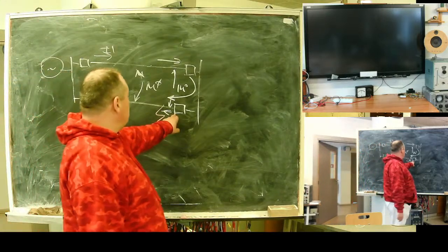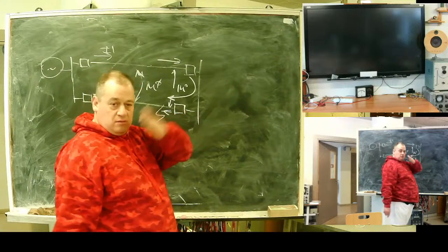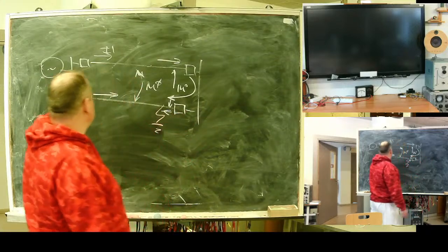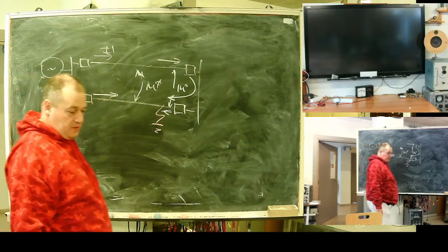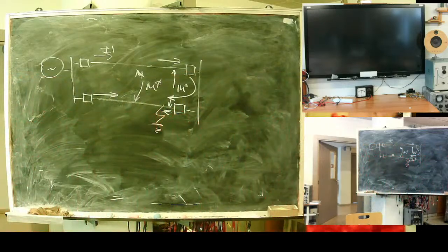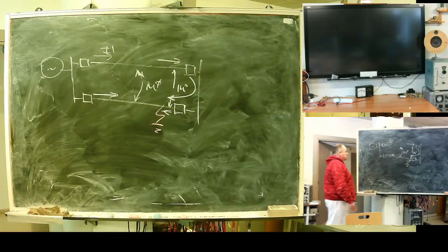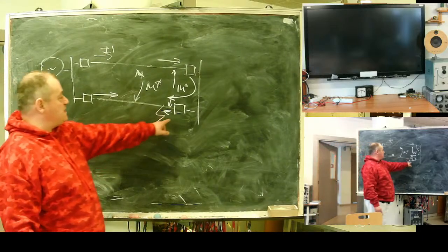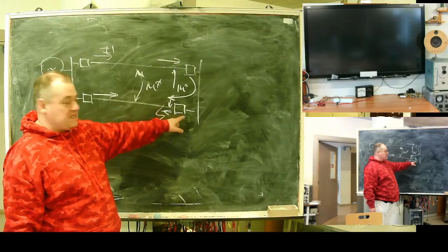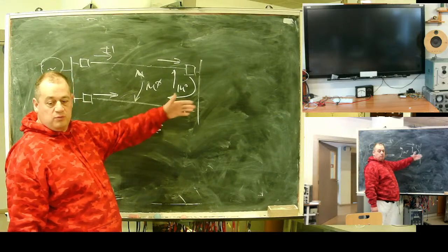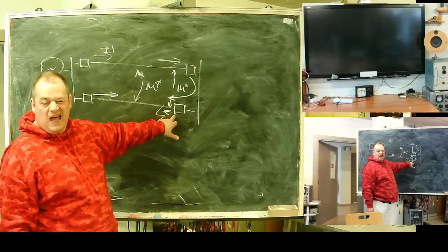And for this relay, fault moves closer. For this one, moves forward. It is possible that you will get strange behavior, not operation of those as intended. One of the things you need to check is for cascade operation. So if for this relay resistance decreases, it will see closer. So fault moves forward, this relay works faster.